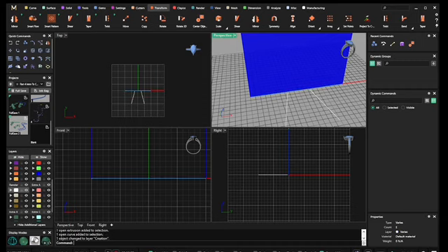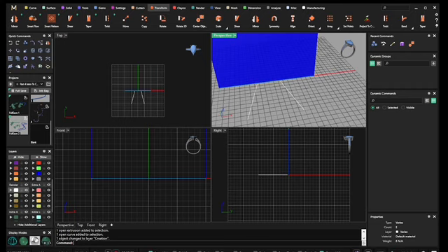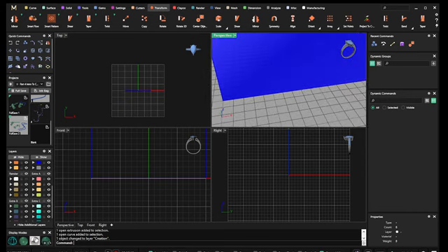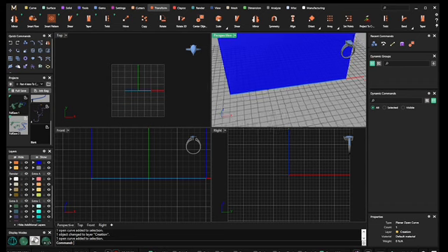I'm going to select that. I'm going to turn it yellow, and I'm going to make the dark green the default and turn off the white so that it's not in the way. All right, so this is now yellow. You can see, well, you can't see the little pop-up. But when I clicked on it, it wanted to know, do I want to click on the curve or do I want to click on the extrusion, which is the surface?